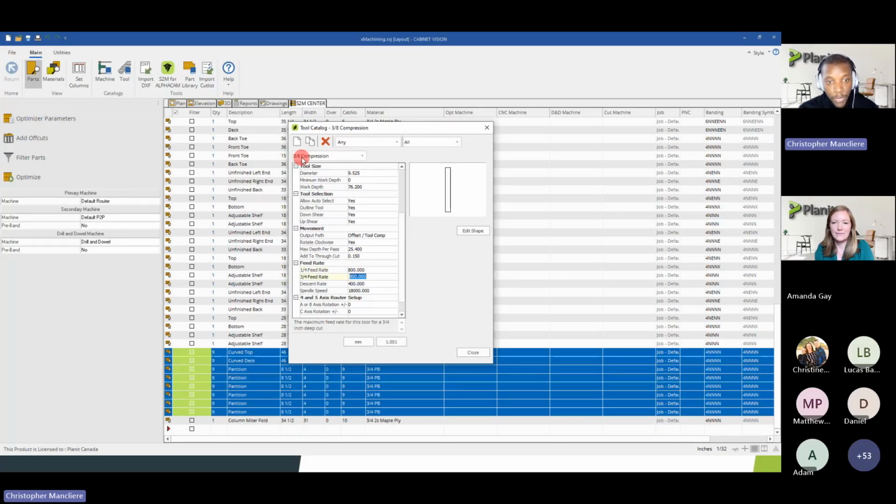And for the compression, it makes sense because this tool will only be used to cut through, and I'm typically always going to cut about 3/4 of an inch of material at once. So I kind of know that I will cut this, and I just set the nominal value, the optimal value for this speed, because I'm rarely going to cut only a 1/4 inch deep.